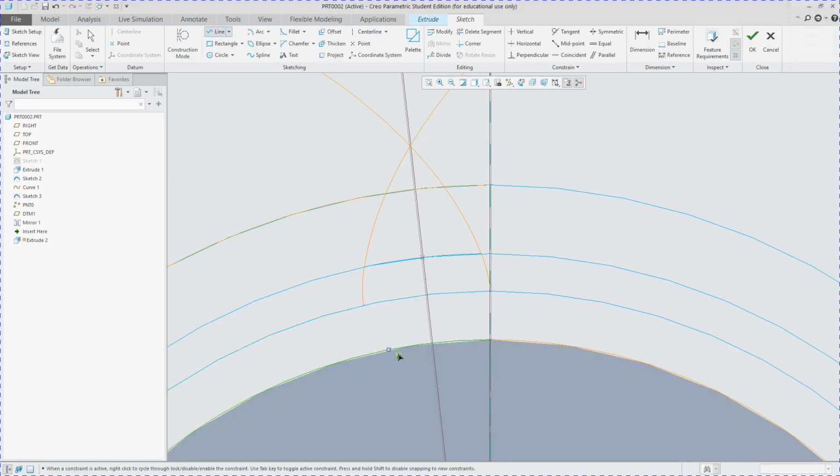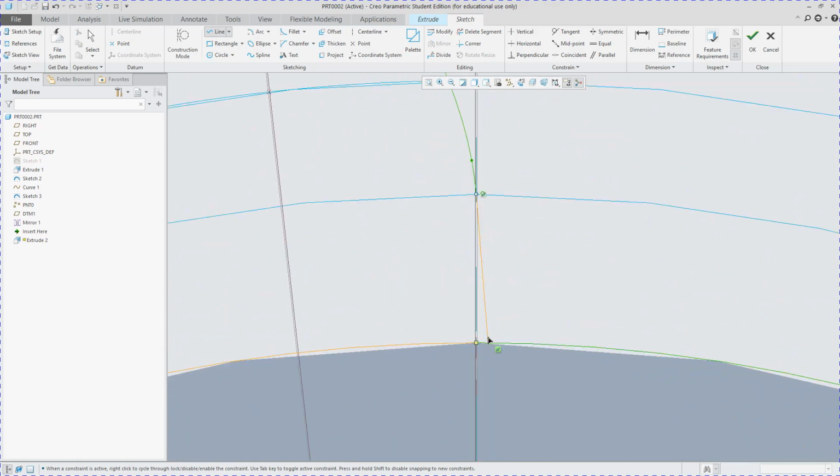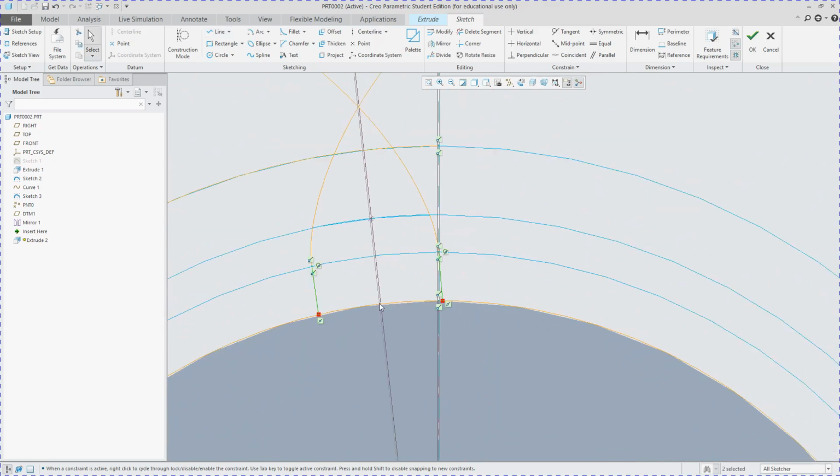And now you see this isn't a closed shape yet, so we're going to take a line, and you want this tangent lock, so it needs to be tangential to the base of your involute. And we're going to try to close that gap. Yes, this can be very, very finicky. Okay.